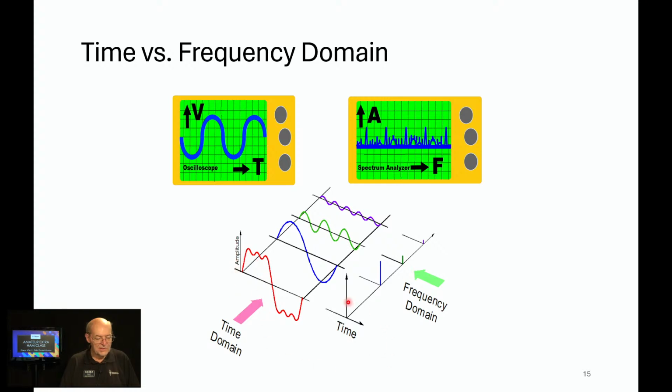What we're showing is the odd harmonics: this is the fundamental, the third and fifth harmonic. If you add those all together, and this is a picture of the frequency domain over here, fundamental, third, fifth, seventh, etc., in the time domain it starts looking like a square wave, kind of proving Fourier's principles.